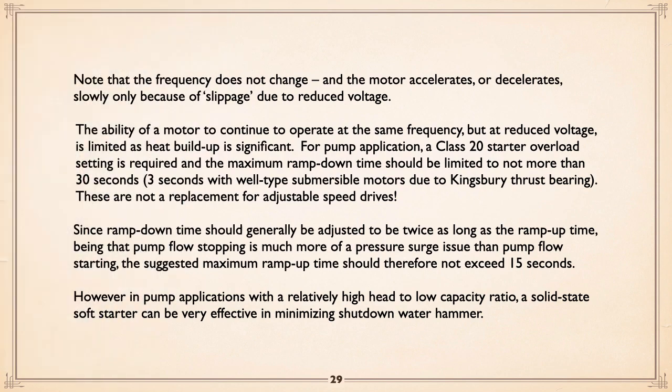The frequency does not change, and the motor accelerates or decelerates slowly only because of slippage due to reduced voltage. Solid-state starters are not variable speed. They are reduced voltage starters that have their benefits. So biggest, number one, they're more controllable. Number two, they can do a ramp down, which is significant. Okay. Now for pump applications,